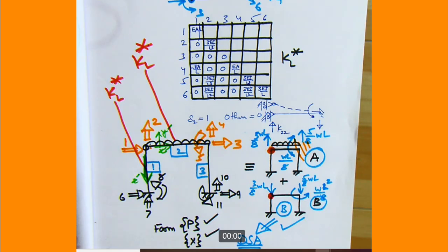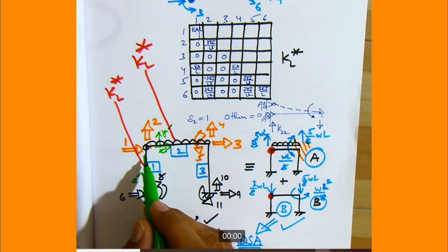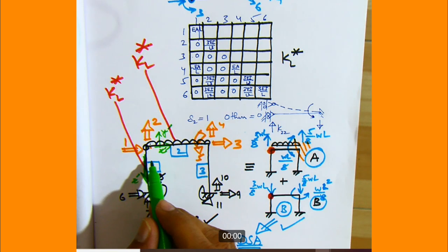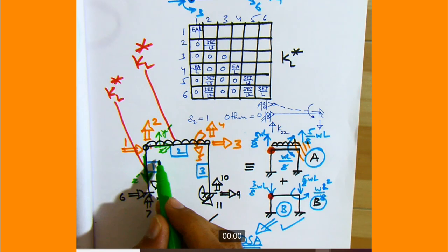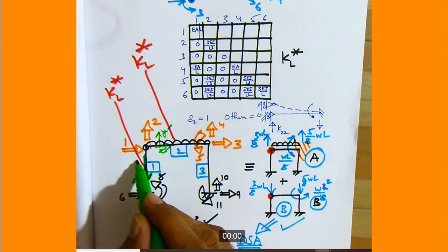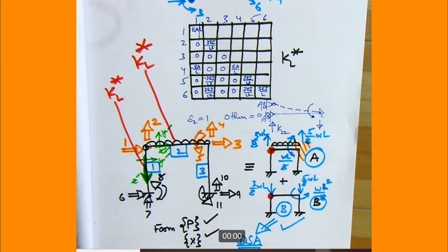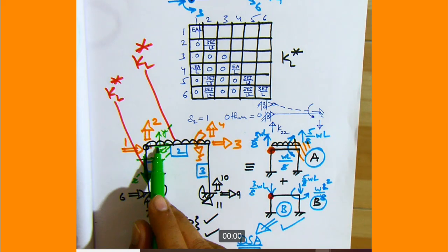And where will the local y axis be now? To the right or to the left? Right. Yes, it has to be towards the right, because x cross y will be z, towards you. So this is how we have to define the local coordinate system for members 1 and 2, because they have hinges, and that's why especially we have to define it like this.